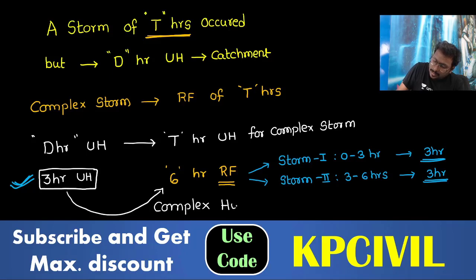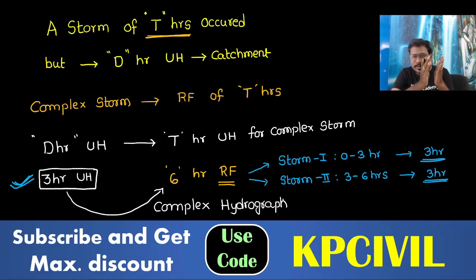This is called complex hydrograph. You understand it? From a storm of D hours already plotted against a rainfall for a catchment, that is called D hour unit hydrograph. When a future storm of T hour occurs and is analyzed using this D hour unit hydrograph, that is called complex hydrograph.